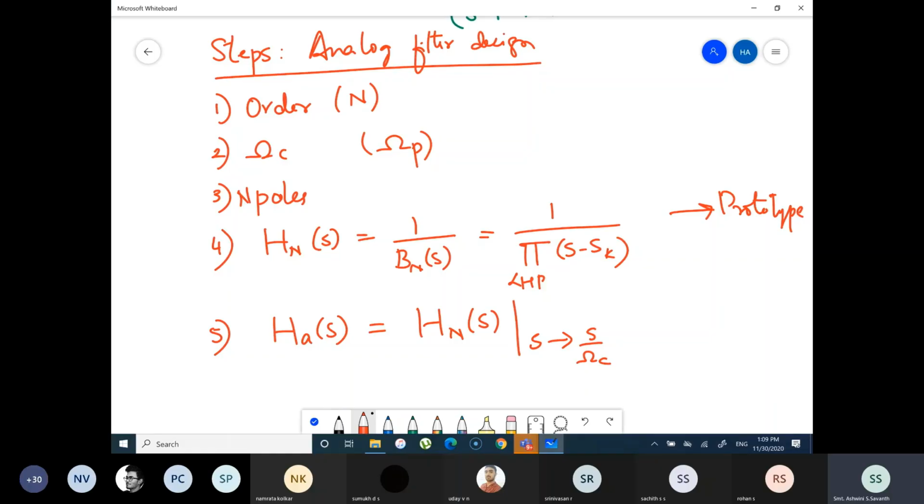Next, for the digital filter design, we are interested in designing digital filters only. But this is the procedure that we follow for an IIR filter. First, you should understand how to design the analog, and then we are going to concentrate on designing the digital filter. So when you are designing a digital filter, there are going to be steps added in the beginning and in the end. Why in the beginning? Because the analog specifications are given to you and you designed this filter now, isn't it? Whatever data was given to you was the analog specifications.